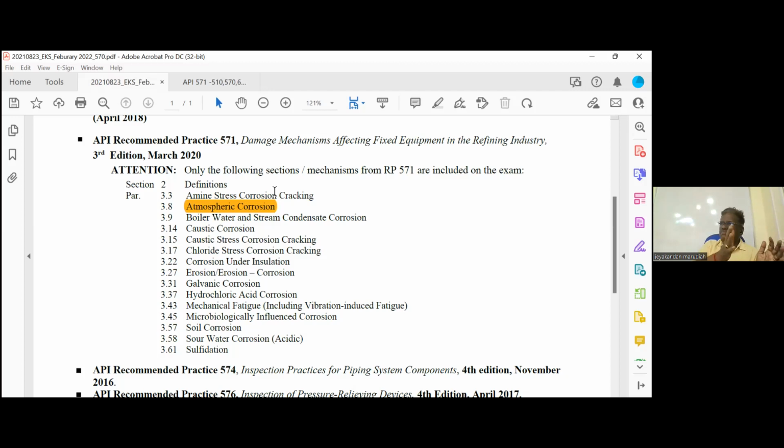So we covered material and critical factors. How will the appearance be? There is no special appearance actually. It may be a localized corrosion or uniform corrosion. Then which NDT will detect it? Again, there is no special NDT. Visually we can see, if it is not insulated, or we can do the UT thickness gauging. For small pipe we can go for radiography also to measure that. That's all for atmospheric. Generally, atmospheric corrosion will have 1 or 2 questions. What are the key points I said? You have to remember.